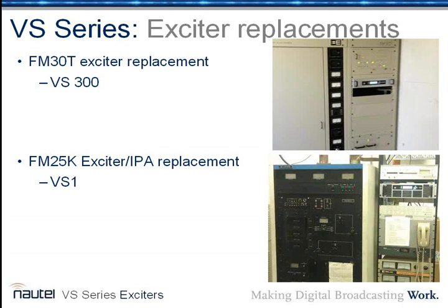So we have that on and filament on. Yes, we do get a little bit of a VSWR spike and it still runs, but as soon as you press plate on, then it ramps up. If we were to just have it turn on at the time when you press plate on, the ramp-up time is too high for it to start sending drive into the final before the transmitter says, uh-oh, and shuts itself down. Fair enough. Okay. Did you notice any difference in, or did you measure synchronous AM noise?